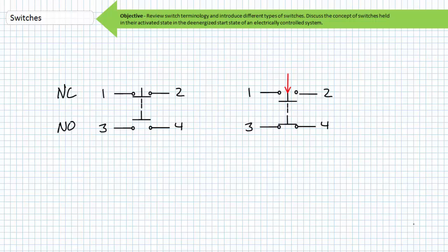However, when an operator actuates a single button on the outside of the package, the normally closed side opens and the normally open side closes. Think of this as 2 electrically isolated, mechanically interlocked switches, both with double break contacts. This is often called a break-make push-button package because when you actuate the single push button, the top switch opens and the bottom switch closes.